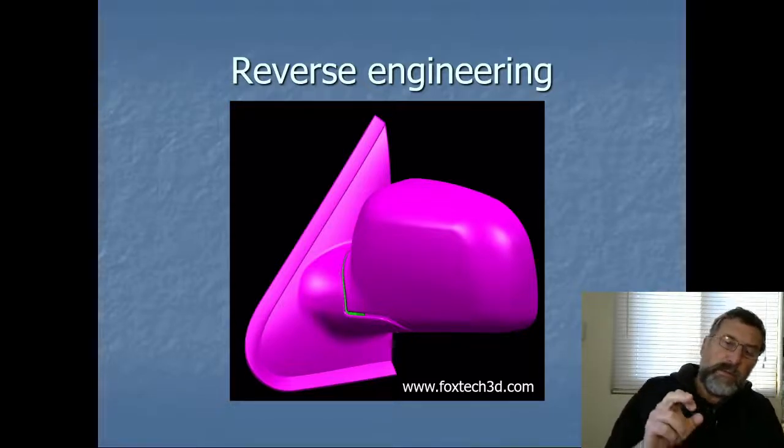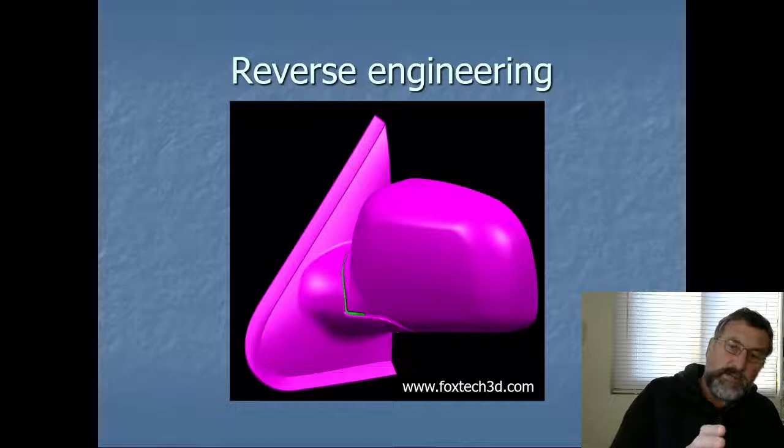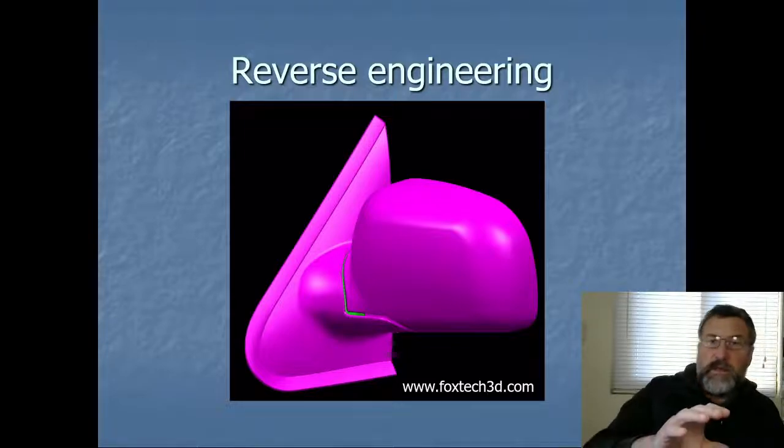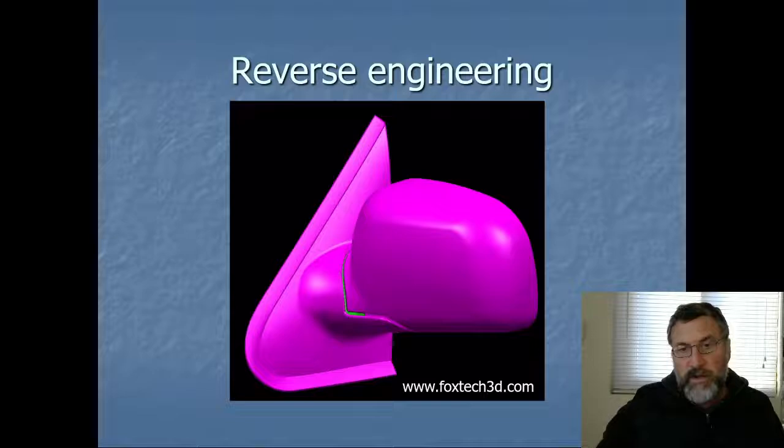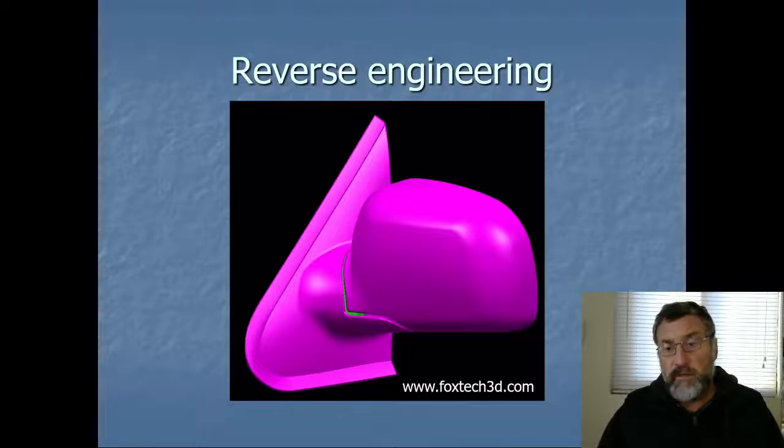And so it just tells you when you come into contact with an object. And then the position encoders on the coordinate measure machine axes tell you exactly where you are in 3D space. And then you can move along tracking a surface and measuring surfaces very accurately. And coordinate measure machines, if you've got the right controlled environment, can measure very accurately down to a micron, say.